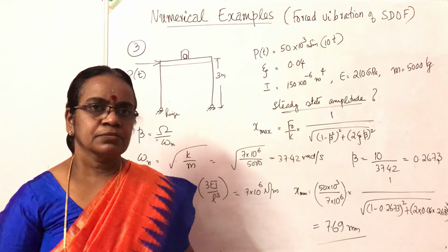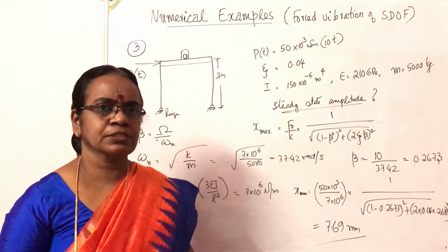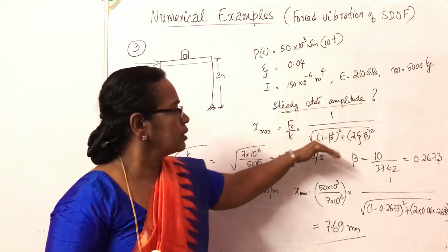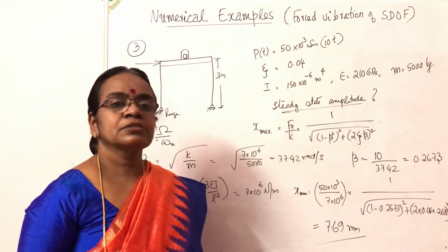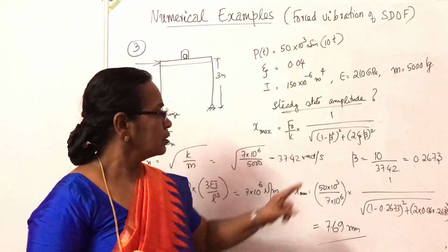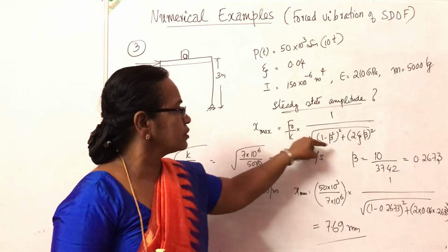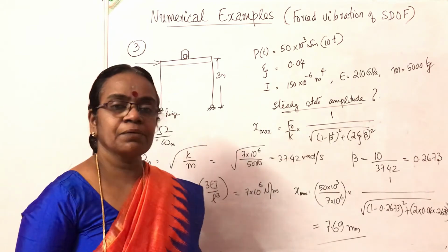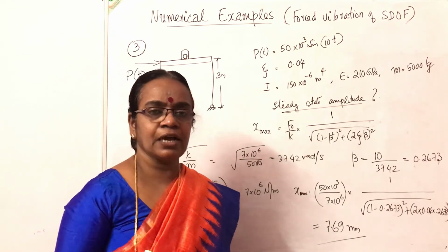So all the three examples which we have discussed now are based on this only one expression. The static displacement times the amplification factor or the magnification factor will be the dynamic displacement or the steady state amplitude.